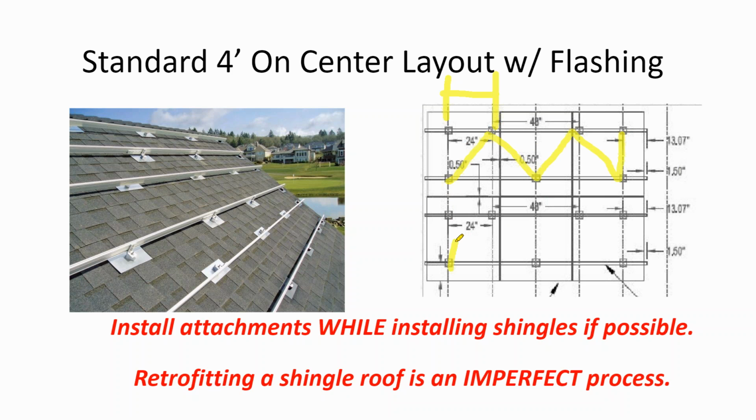If you have 2 rows of solar panels and you're 4 foot on center, it really doesn't matter the spacing of your rafters, because instead of going every other, you can go 1, 2, 3, 1, and then hit every rafter as you go across so that you evenly distribute the load over the truss of the roof.